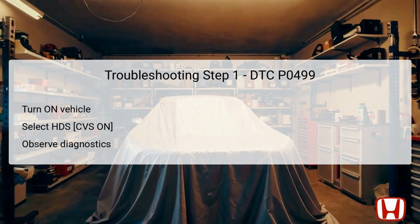This procedure enables the technician to observe and retrieve diagnostic data pertaining specifically to the EVAP canister vent shut valve. Monitoring this data provides insight into whether the valve is receiving the appropriate signals and whether it is functional. Should an issue arise during this step, the technician can identify abnormalities in the circuit operation, which will inform the next steps in the troubleshooting process.